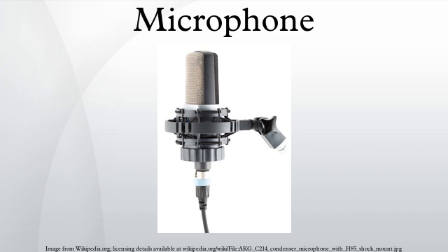Dynamic microphone. Dynamic microphones work via electromagnetic induction. They are robust, relatively inexpensive and resistant to moisture. This, coupled with their potentially high gain before feedback, makes them ideal for on-stage use. Moving coil microphones use the same dynamic principle as in a loudspeaker, only reversed.